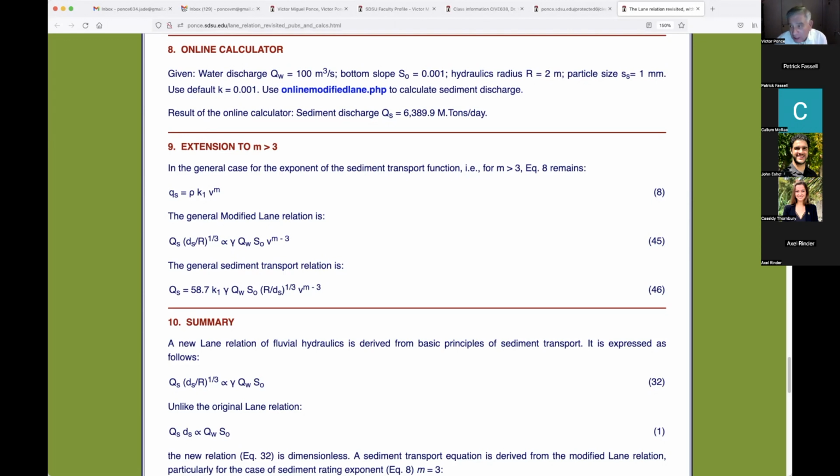Now, from 3 to 7, being an exponent, that's a lot of influence, because imagine 2 to the 3 is 8, and 2 to the 7 is, I calculated the other day, 16, 32, 128. So the ratio is between 8 and 128. That's a tremendous ratio. And the justification is that sediment transport does vary a whole lot. And that is why it is difficult for us to pin it down.